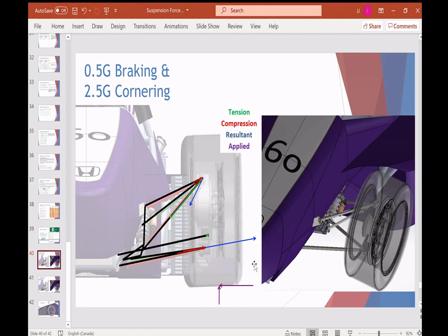If you're trying to look through the code, one thing I'll mention is that I do use named ranges a lot, so you'll have to work those out. And here you can actually see that our pull rod, which is this arm here, is increasing significantly because our upper control arm is at a very low angle. And as these two become more and more in plane, the forces are going to get higher and higher. And this is one of the reasons why we can't look only at the pull rod forces using similar triangles, because these upper control arms are increasing that force very significantly.